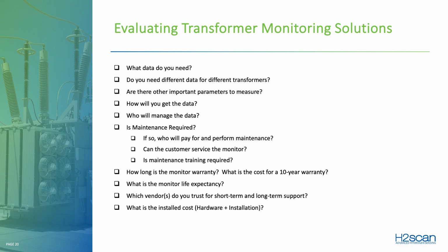Are there other important parameters to measure? A lot of people are moving to very reliable systems where they just have a bushing monitor and a hydrogen monitor because, depending on who you're getting your multi-gas monitors from, a lot of them require a lot of maintenance, and that, of course, is not preferable. I've heard a lot of customers say that they're tired of maintaining their monitors more than they're maintaining their transformers. And so that becomes a big issue. And so having good, reliable monitoring is important.